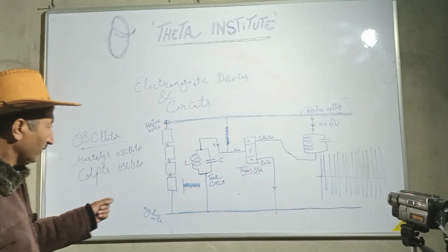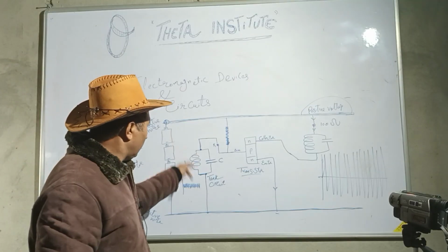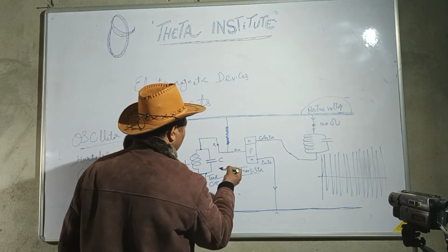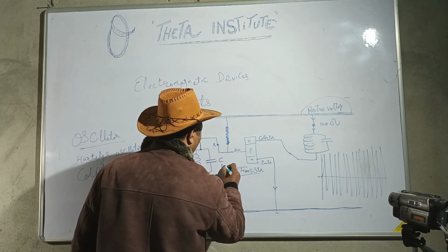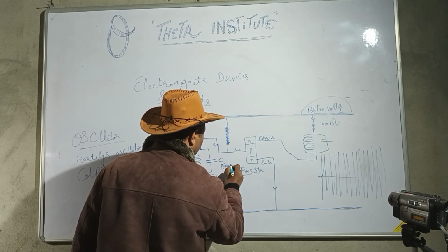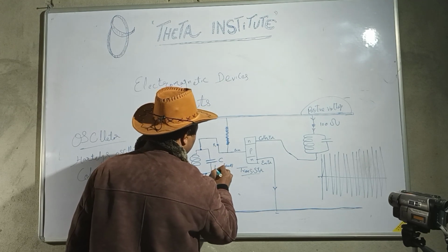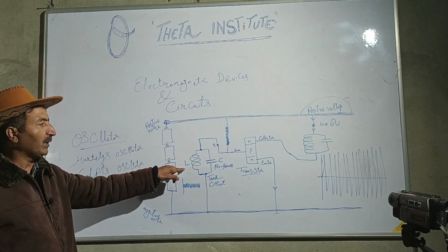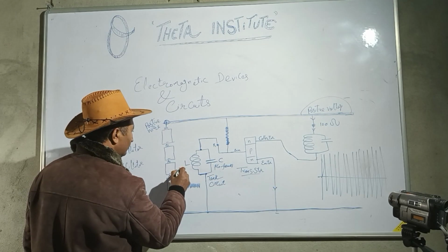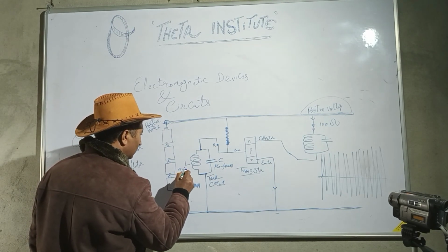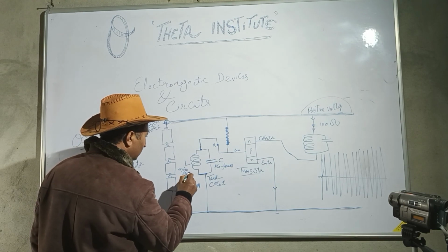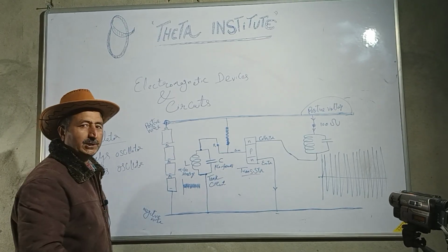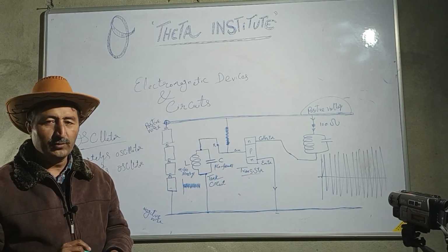However, if it is so much smaller number of turns and so much smaller a capacitor of a few picofarads, pico means 10 raised to minus 12, if it is in the order of picofarads and in microhenries, what emerges from it is a high frequency, a radio frequency.